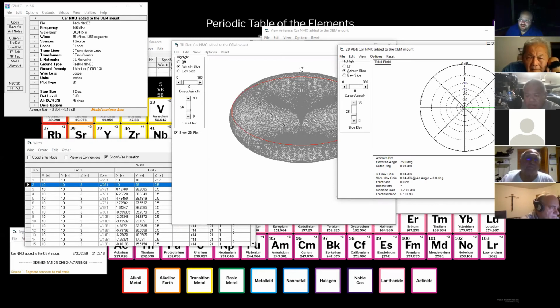Is it really worth cutting that many radials for something like this? That's why when antenna designers put together antennas that are going to go in the air, they do the 4 tuned radials, because that gets you a reasonably effective pattern, but it's not all that much work to put together. You don't have all those materials costs there. But now if you are doing one on the ground, that's where it starts to make a difference, especially with these big, long, low frequency antennas where you're trying to use the ground to fill in the blanks and everything else. But in the design, I rarely run more than maybe 8 radials in the computer design.